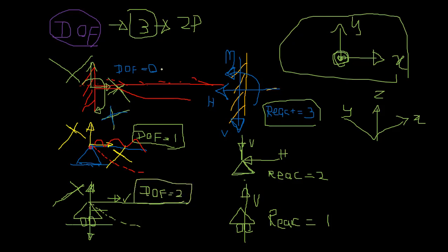So can you see there's a relation, right? Summation of these two is always a constant, right? At a joint, degrees of freedom 0, reactions 3. 2 degrees of freedom restrained, so that means there should be 2 reactions. So the reaction should be there to restrain that degree of freedom. That's simple as it is, right? So one will be left at a pin support, so that is the bending moment, right? It can rotate, so that means it does not provide any restriction to bending or rotation.